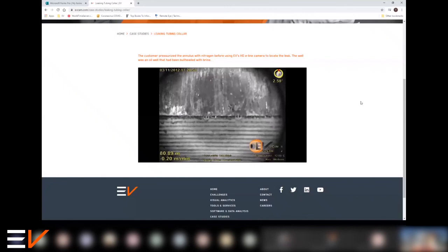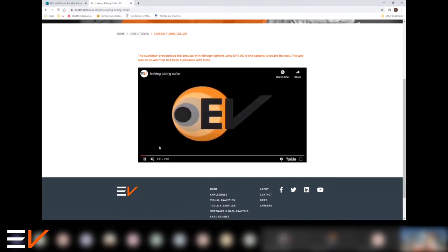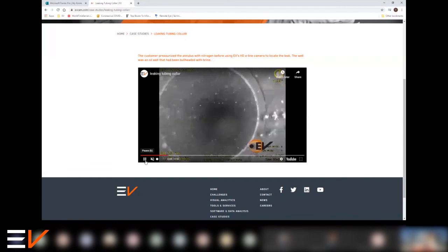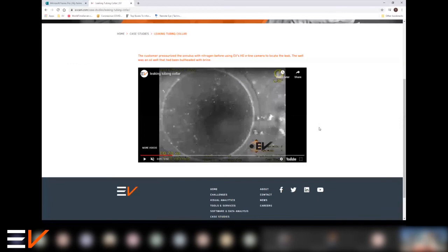I should say as well, this is a tiny leak. This is a small number of gas bubbles in a very, very large volume. So other techniques, including things like acoustic leak detection surveys, which I know very well from a former life, these sorts of things are quite hard to locate. But with a combination of those sensors, you can hear it on the acoustic tool, you might be able to detect it on a thermal tool, and you can see it happening with the camera. All of that you could achieve potentially in real time from a combination service.